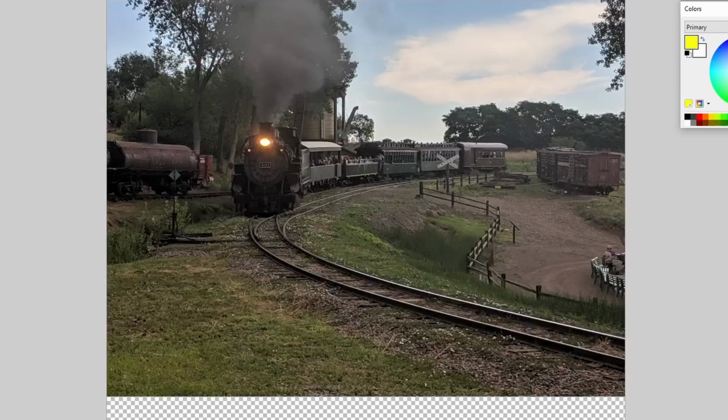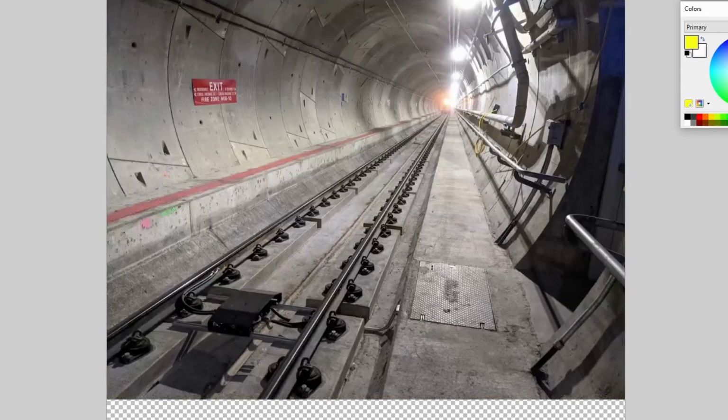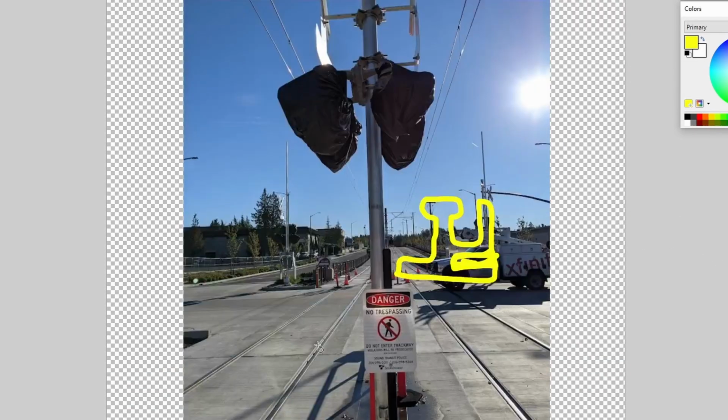We have many different types of track using all these techniques and things that we've talked about. We have at-grade ballasted track like this, where the track is at the grade. It's not a bridge, it's not a tunnel, and it has ballast that holds it in place. We have direct fixation track, where the track is directly fixed to the ground, each rail individually, without even the use of cross ties. And then we also have embedded track, where the track is sunk into the ground and typically has an extra special rail profile to ensure that we can pour concrete but also maintain our flangeway.